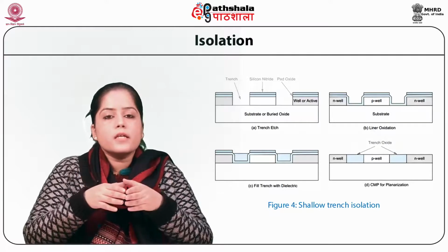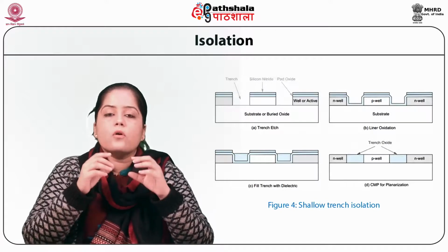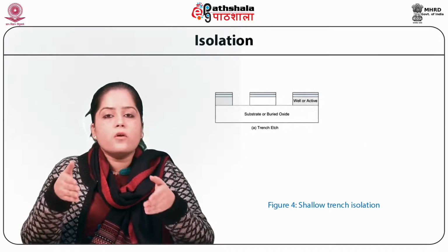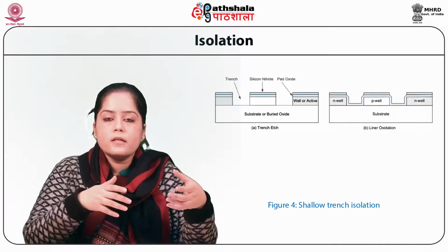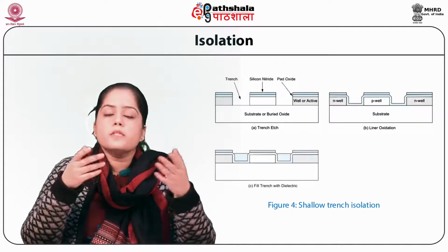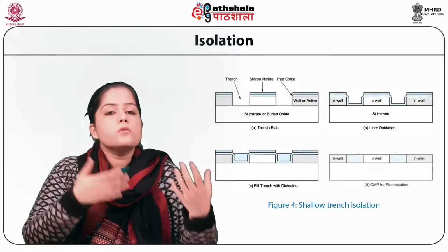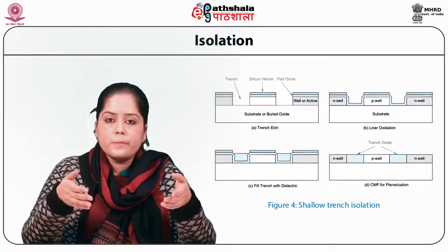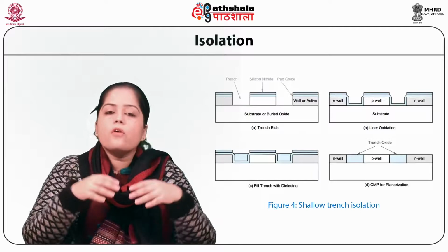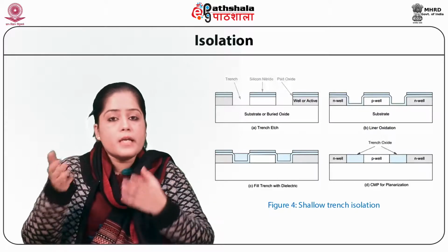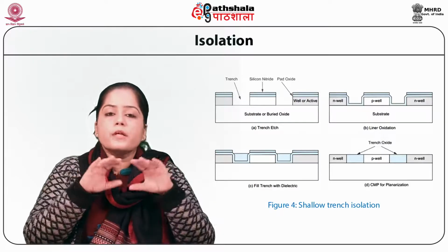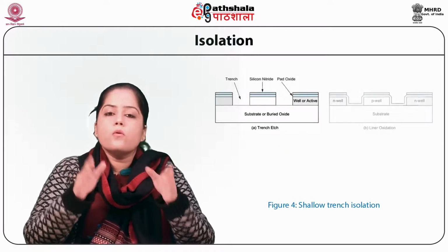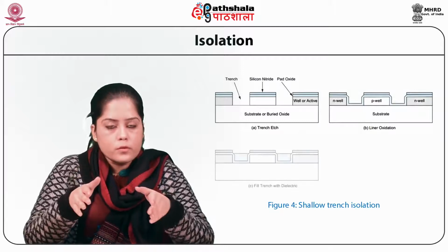The transistor gate consists of a thin gate oxide layer. Elsewhere, a thicker layer of field oxide separates the polysilicon and metal wires from the substrate. So the source and the drain of the transistor form reverse biased PN junctions with the substrate, well isolating them from their neighbors. The thick oxide is formed by a process called local oxidation of silicon (LOCOS).